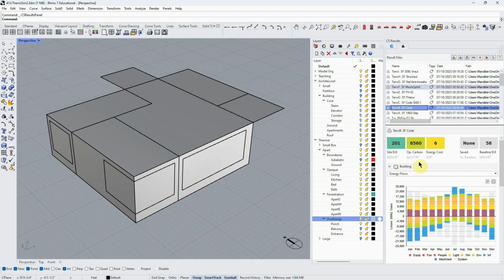Okay, then what did I do next? Next, I just changed the glazing to be double pane 90.1 standard glazing. Whenever I say 90.1, that's the contemporary baseline energy code standard. So it's good, not great. Lots of projects get to it, but it's not 1960s. And so when I change that, I get a pretty hefty improvement to 181.